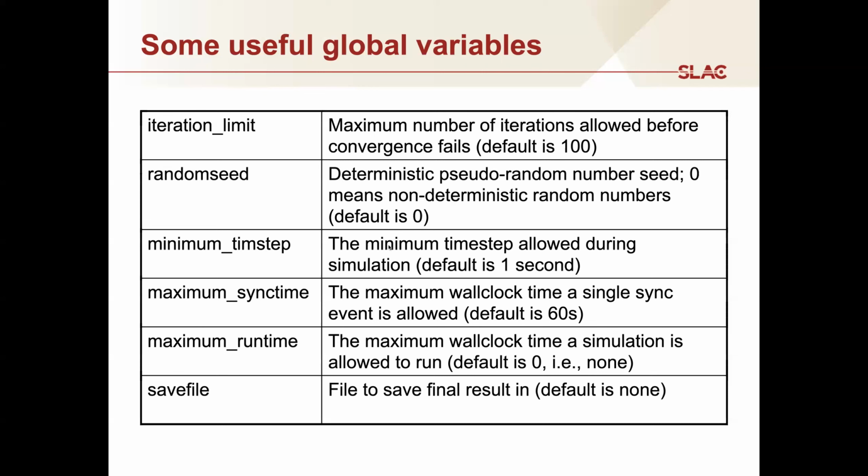Let's see, minimum time step allows you to control, we talked about the time stepping mechanism, the smallest time step it's allowed to take. Apologies for the typo. This is time with an E. The default is 1 second, but you can increase it to 10 seconds or a minute or even an hour if you want, depending on the type of objects that you're dealing with and their dynamics. You can essentially exclude certain dynamics from your simulation. And that can have very beneficial performance effects.